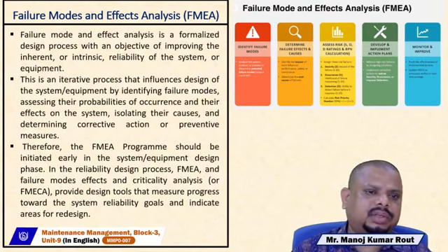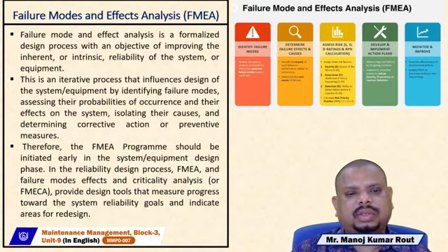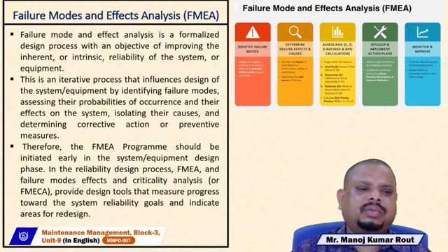Moving to the next one, how failure analysis is used by various industries. Failure mode and effect analysis is a formalized design process with the objective of improving the inherent and intrinsic reliability of systems or components. So this is an iterative process. A number of steps are there, and it influences the design of the systems or equipment by identifying the failure modes and assessing the probability of occurrence and their effect on the system. The next one is isolating their causes and determining the corrective action or preventive measures.